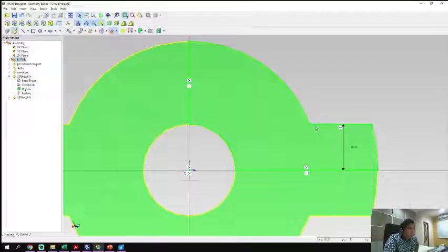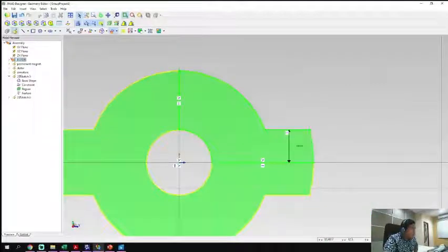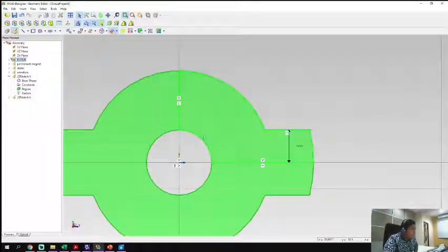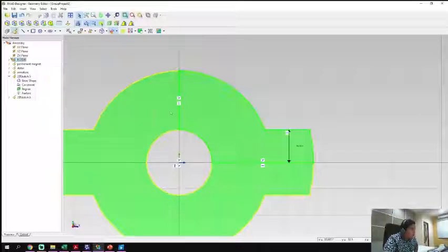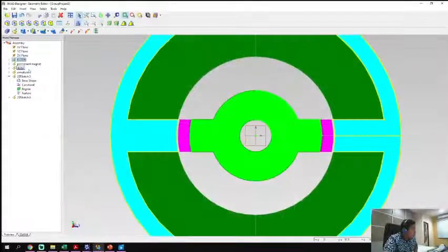And then we create a region here, we delete the inside part, we trim it here, so we get a reverse L shape. So we create a region, and we mirror it to this line, and we merge it, so we get a half hemisphere, and we merge it in this line, so we get the full circle here. Alright, that's for the rotor part.